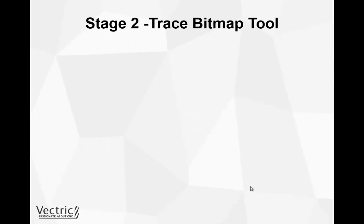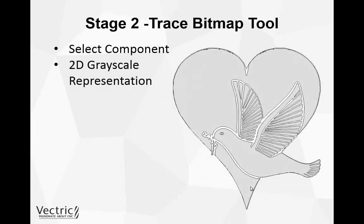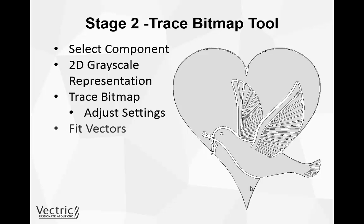Then we move on to stage 2, where we use the Trace Bitmap tool. So what we do is we deselect any models that we had ready for toolpathing, and then we select the new component that we just created using stage 1. We then use the 2D grayscale representation of that model, and then we go to use the Trace Bitmap tool. We adjust the settings, and then we use the tool to fit vectors around the raised areas in our difference model. So as you can see in this little picture here, you'll see that the vectors have been fitted around all those raised areas that we had on this model.